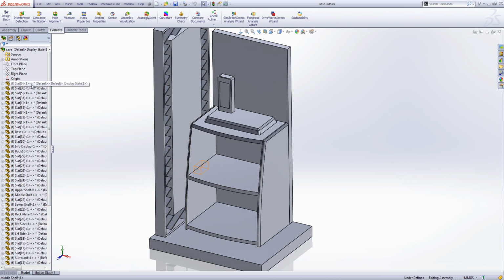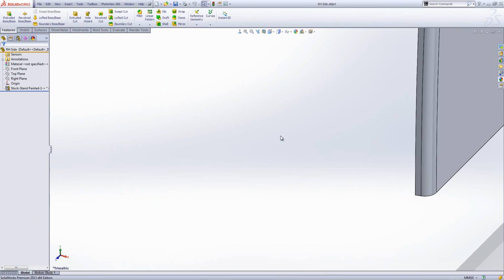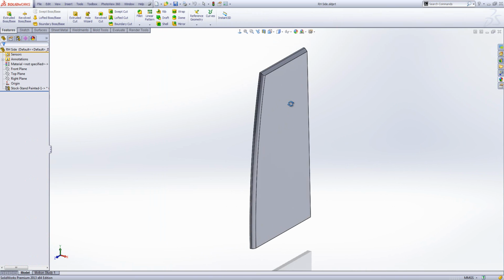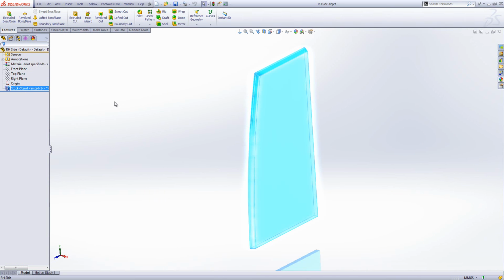And what we've also got in here is an external reference from each one of these part files. So if I was to open up one of these, for example, you'll notice that external reference gives us all the kind of features, but just with this stock feature on the left. That stock feature takes all of its shape from the original part file with the external reference so that it links back to the original, and if any changes are made, it will update automatically.